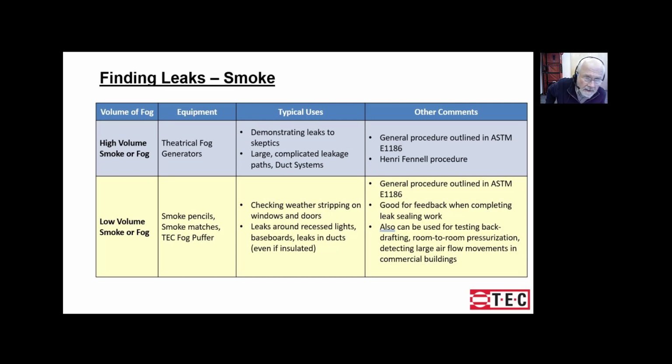Okay, so in that video, I thought the most interesting thing was Jim thought he had sealed the leak, but then he checked with smoke and he found that the next joist space over now became the leak instead of the leak that he sealed, and he didn't stop sealing until there was no more smoke going into any of the leaks. And I think that's something that anybody doing a lot of air sealing, especially in existing houses where things are dirty and there's insulation in the way, it really helps you see what you're doing.